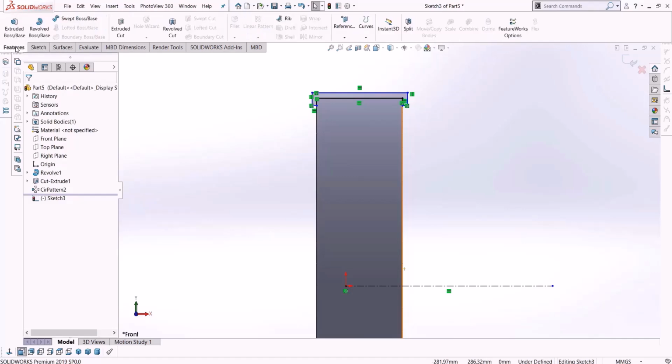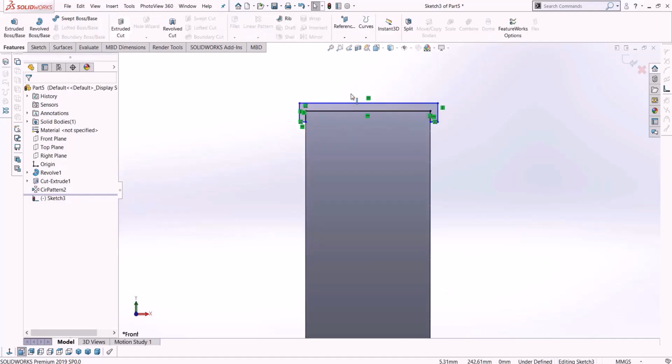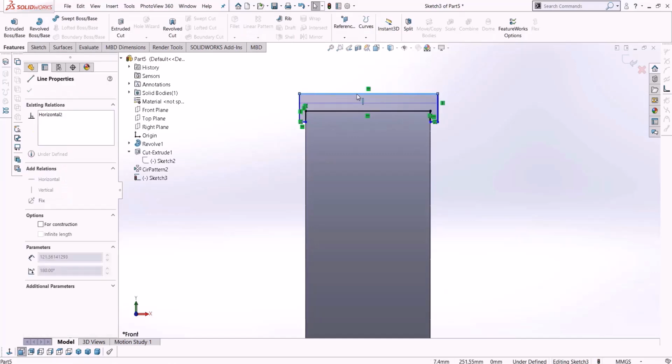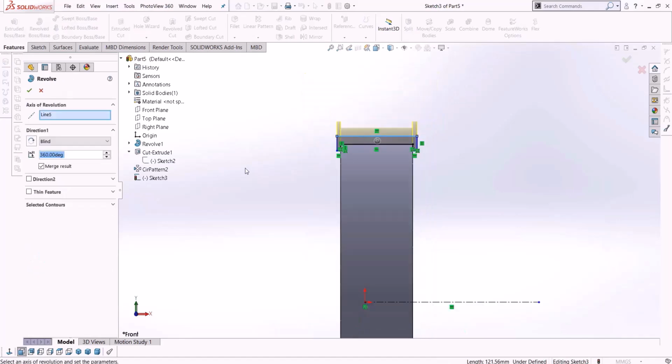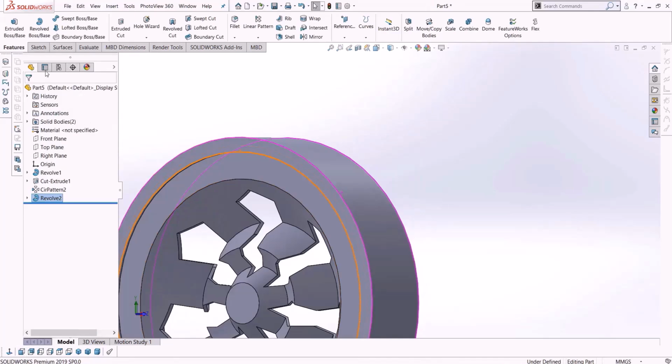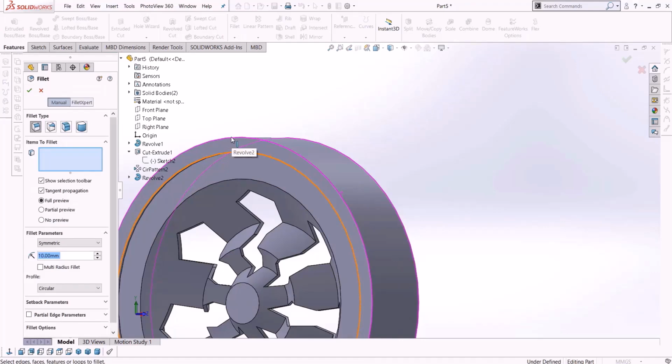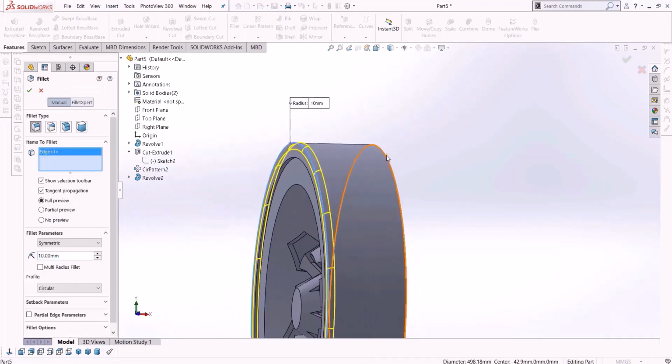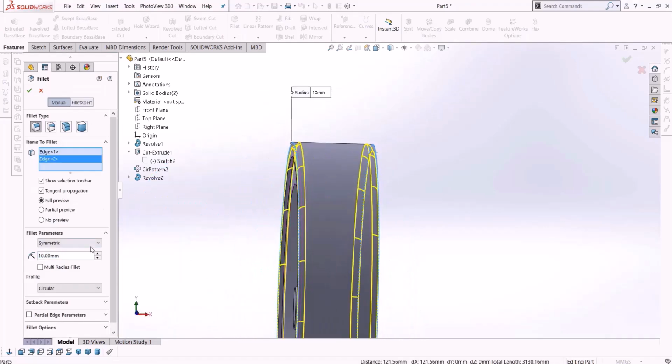We drew something like this here, and I have a connection to a counterpart. I hit the okay and it asks if I want it to merge into the existing body. I say no, because I want this tire to remain separate, and then I apply a fillet to the edges to make it look a bit more natural.